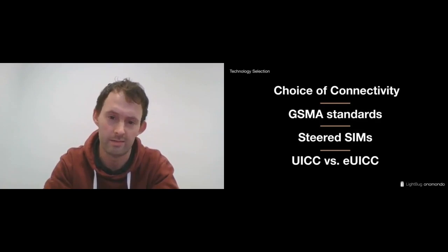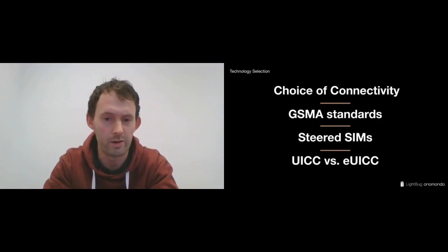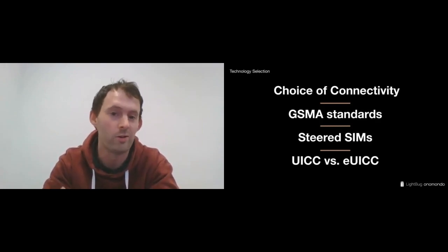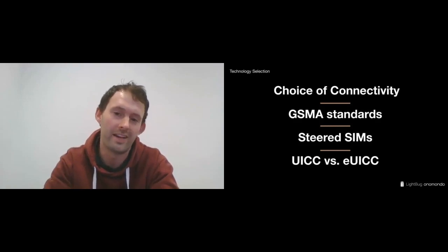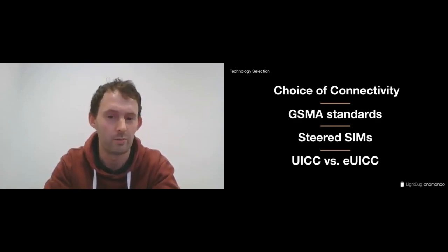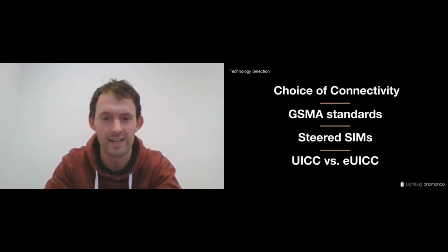The steered SIMs use an onboard logic that requires the cellular modem to interpret the commands to do something with that steering, and the modems that we were using from a pretty well-known manufacturer just weren't working. They were ignoring the steering commands. And so what ended up happening is that we would have devices that would stop connecting, and they would need a physical reset or a physical input, which in the world of IoT is